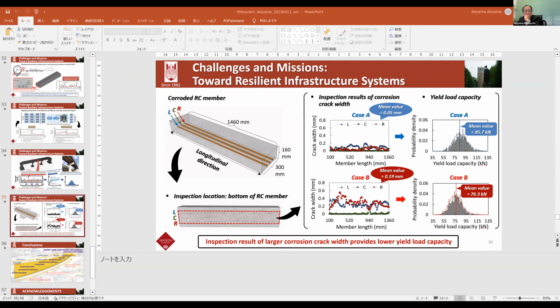Also, the point to consider is that finally, we cannot remove all uncertainties. So the decision makers have to make a decision under uncertainty. This means we also have to study more about how to determine the threshold, such as failure probability. And also in life cycle analysis of concrete structures, we have to take into account many kinds of uncertainties. Currently, uncertainties associated with hazard assessment, such as earthquake and tsunami in Japan, we should consider these two big hazards. But these hazard assessments include very large uncertainties.